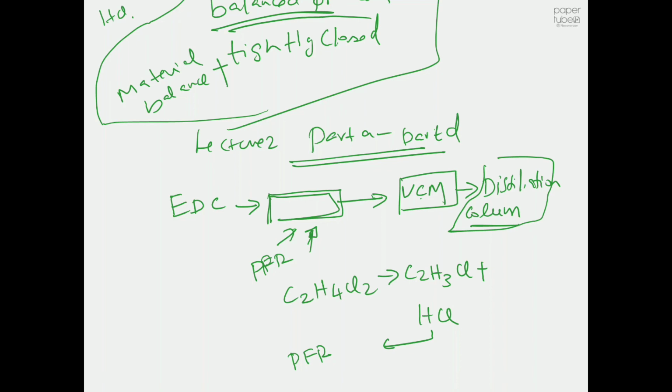These are the information that you need when you design the distillation column, and also in which stage your feed should enter. This type of thing you can calculate very easily using Aspen HYSYS. There are a few tricks to that, so I will teach you those tricks, and then we will go on to design the distillation column.